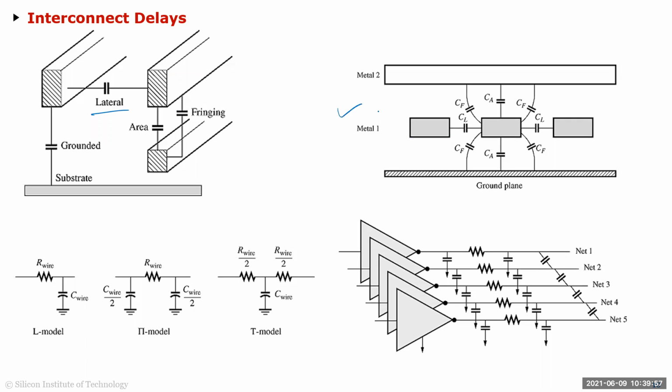This is a diagram showing you what are the different types of caps when you have all these wirings going on, and the different types of models you use to approximate this wire delay caps. And this is showing you, if you have gates and these nets, how the parasitic extractions are done and annotated, and how they'll look eventually depending on which interconnect model you have chosen.